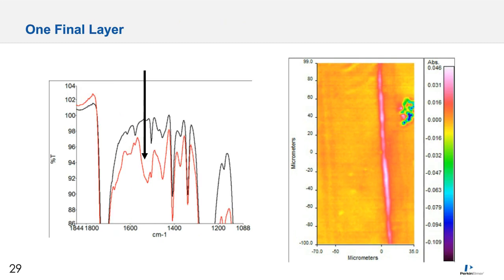And one final layer present in this sample. This layer is actually the linchpin of the product. It's an amide-based adhesive layer which holds the outer polyethylene terephthalate layer to the inner low-density polyethylene layers. Once more, we change the basis of coloration, now changing this to the amide 2 band near 1523 reciprocal centimeters. Now the infrared image shows the hottest colors, as we might refer to it, where this band